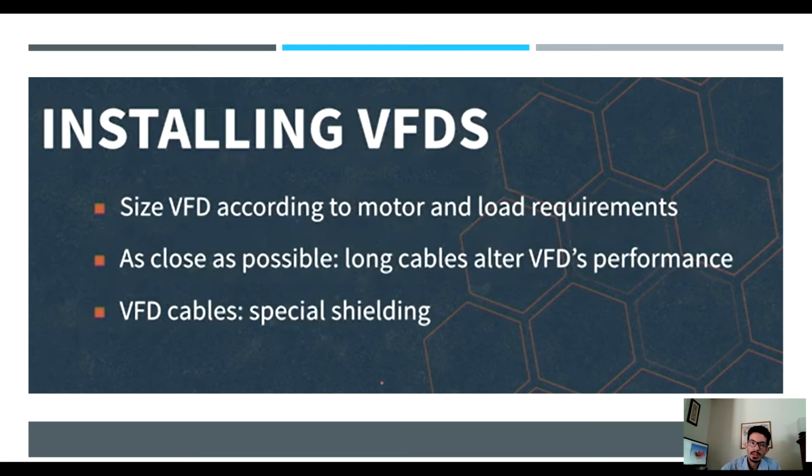In other words, if you want to operate a motor at 60 RPM or 100 RPM, you have to check with the manufacturer and with your variable frequency drive what output the drive is going to give you. Is it going to give you a value of current? Is it going to give you a value of voltage? And then from those variables that you get, how do you map them back to RPM?